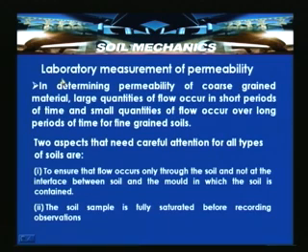So, in this slide, in determining the permeability of coarse grained material, large quantities of flow occur in short periods of time. Because of the large pore spaces, the large quantities of flow occur in a short period of time. Contrary to this, in case of fine grained soils, small quantities of flow occur over long periods of time. So, there are two distinct differences. In case of coarse grained soils, large quantities of flow occur over a short period of time. In case of fine grained soils, small quantities of flow occur over a long period of time.